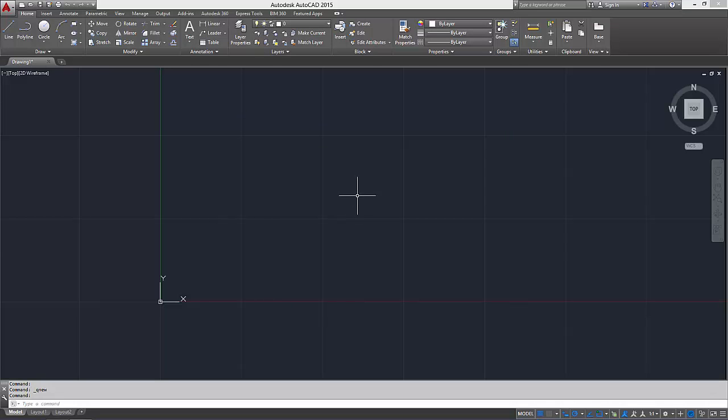And as far as units go, we will be using millimeters. So if you entered 10, then that would be 10 millimeters. If you think in your head that you're working in meters and you enter 10 for meters, then it's still going to be classed as 10 millimeters. Even if you set the insert units to meters, it doesn't mean anything. It just means that the object that's created will then insert based on a scale of maybe 1,000 times bigger or 1,000 times smaller than the objects that you're working on. And like SketchUp, we'll work on full scale. So you draw everything in model space at full scale.